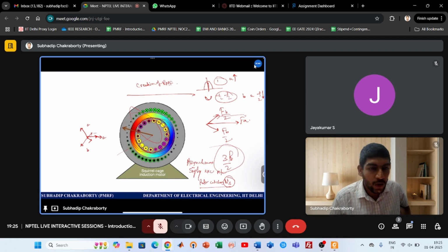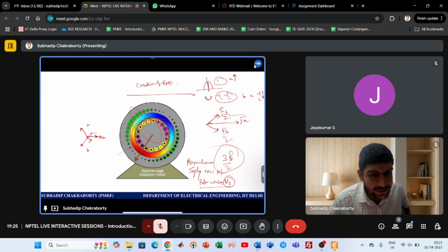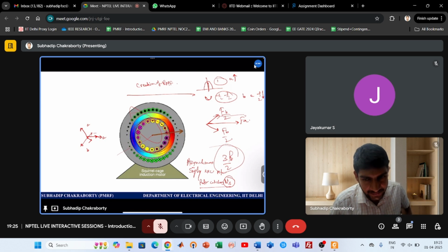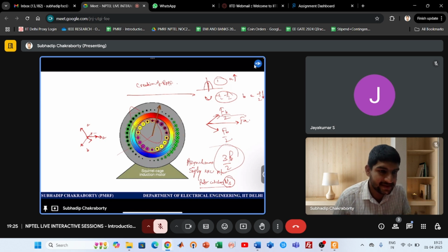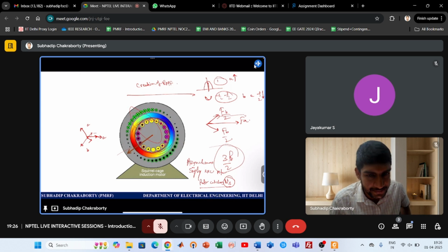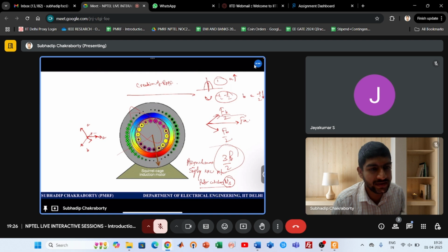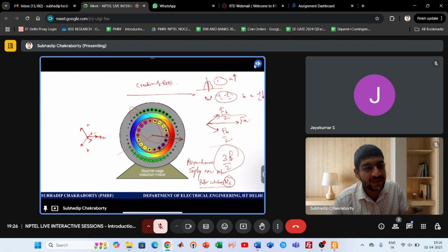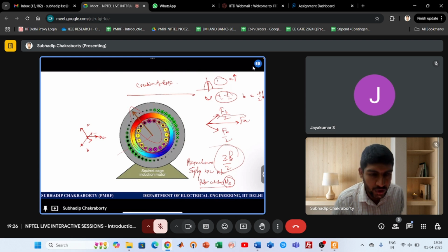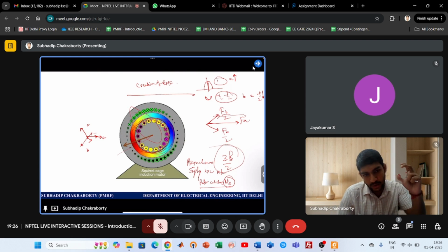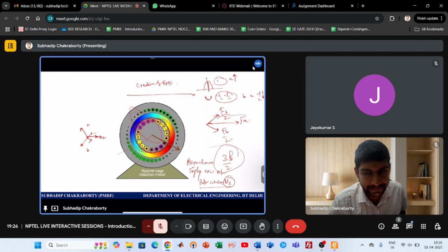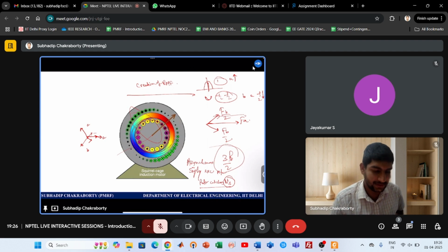Asynchronous machines operate by the principle of Lenz's law. They try to oppose to the maximum possible extent but cannot catch the cause itself. It will try to oppose but not catch the speed itself. Because of the inertia of the rotor, ideally it should rotate at synchronous speed, but the inertia itself creates a load on itself, and it rotates slowly, very close to the synchronous speed at no load, but not exactly at the synchronous speed.